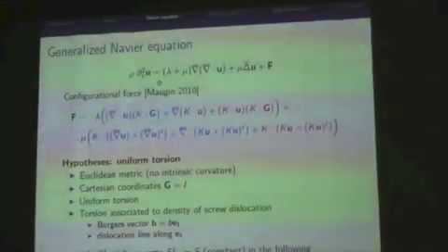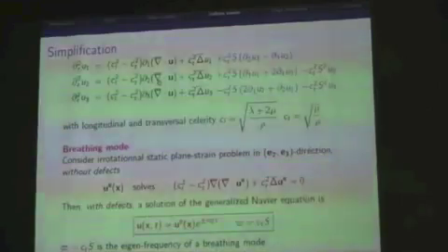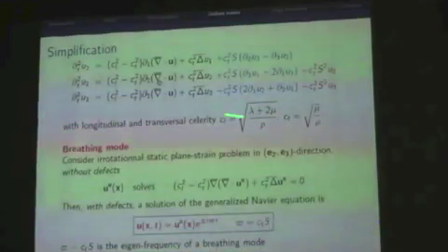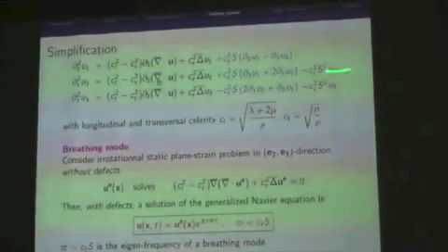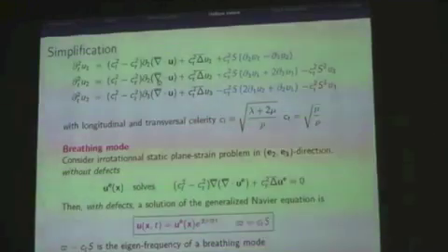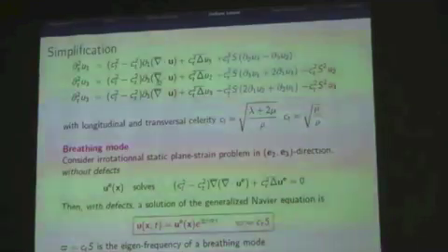In this case, I have only this non-null term, and in the following I will call it S. So, thanks to this term, I write the contortion and I clean up all this equation to obtain this one. Of course, this Navier equation is a wave equation, and we have here the term induced by curvature, and here the other term. The terms CL and CT are related to the longitudinal and the shear waves.